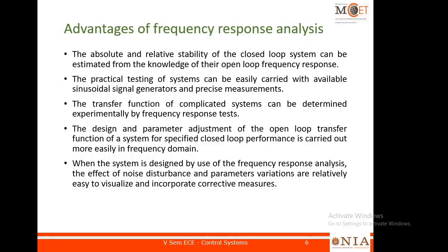Once you design a system, you can test it with the available sinusoidal signal generators at your laboratory. If you design a complicated system and want the transfer function for it, you can experimentally calculate the frequency response of the system, and then from the frequency response you can obtain its transfer function.